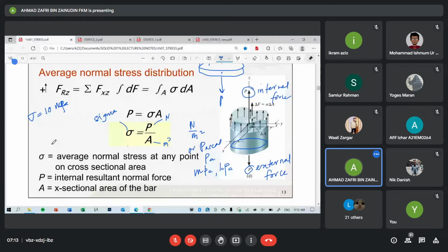If you give your answer like this, because it's positive, normally we don't put a plus sign to represent positive. So we assume that it is tension. If the internal force is compression and you calculate the normal stress, the answer is compression, and the sign is considered part of the answer.